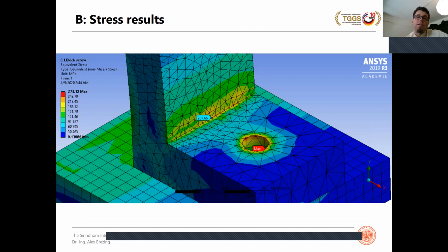Now, the highest stress level in this model is where the head of the bolt is pushing down the aluminum part, but you can just easily ignore that. Typically, when I would show simulation results to a client, it's often a good psychological idea not to show these nodes anyway. They distract, and it's a meaningless stress level at this position. What is really meaningful is what is happening on this edge of the aluminum part.